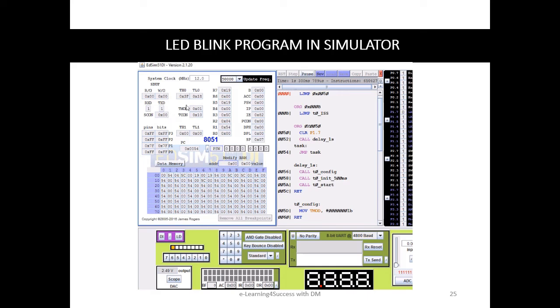You can also study the variations happening in the registers during each step using the method we have discussed in the previous lecture. Again, the point to be noted is that the output obtained depends on the wiring of the LED as well as the program written. You can also pause the simulation at the LED transition times and see the corresponding simulation time.